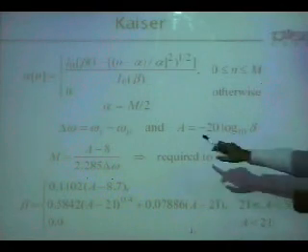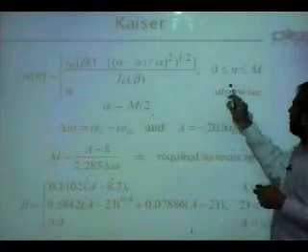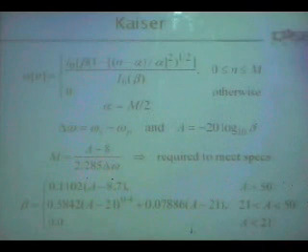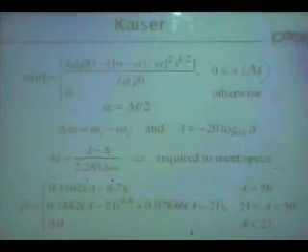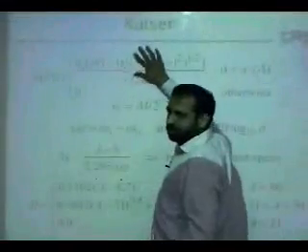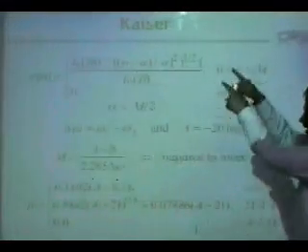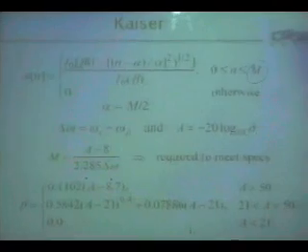Alpha is simply M over 2, the length over 2, but what should the length be? M is a design parameter, obviously. So you are giving specs and you want the Kaiser to come up with the length and the window. The window comes from this function, and I'm saying let's not worry about this function at this point. It's just a curve inside that.